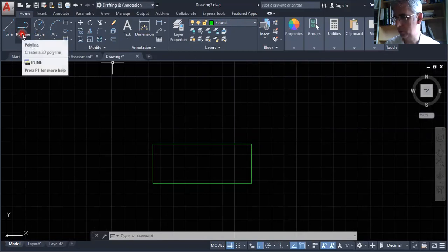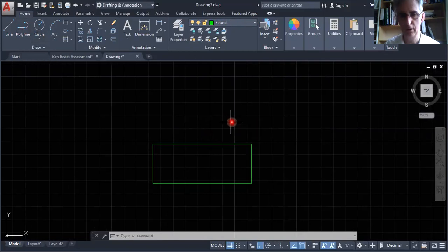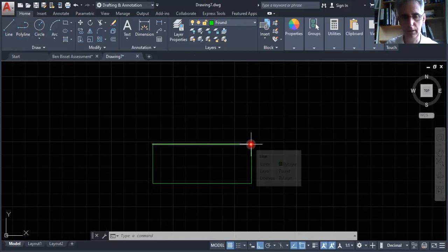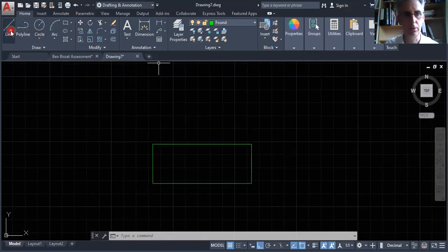I want to create a little bit of a nib here, which you'll see on the PowerPoint that I have given you. It's at the start of your PowerPoint, just a still shot of this little bit here. So we're going to keep going on, and I want you to snap onto the corner. These are your object snaps, these little green symbols.